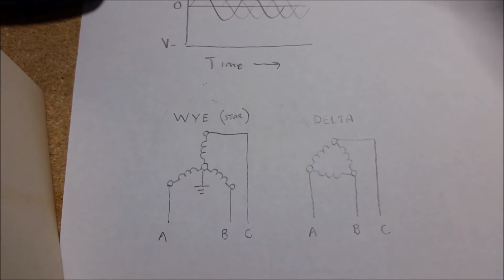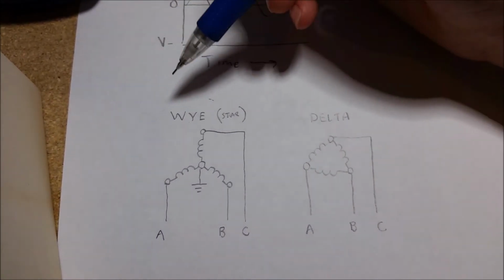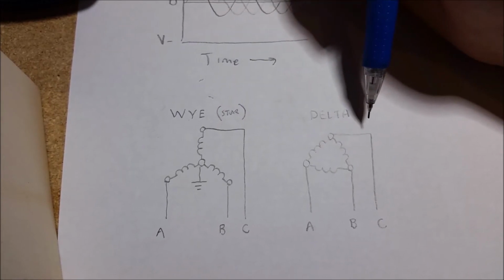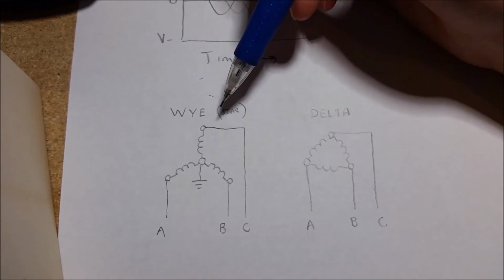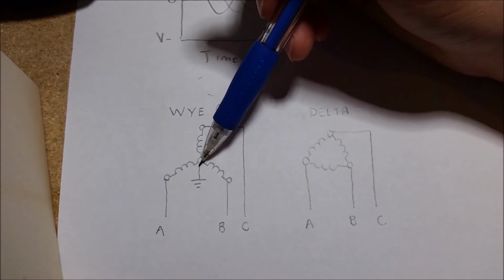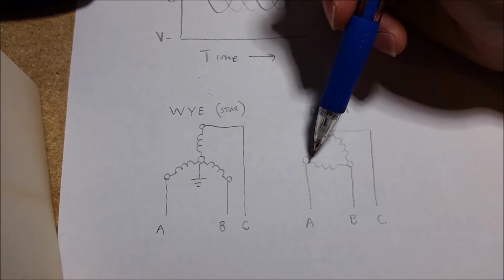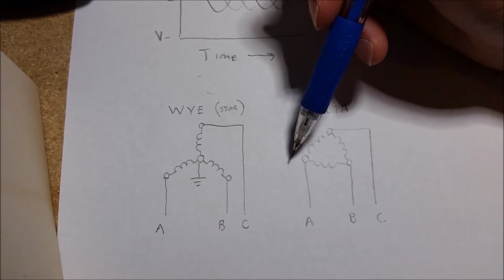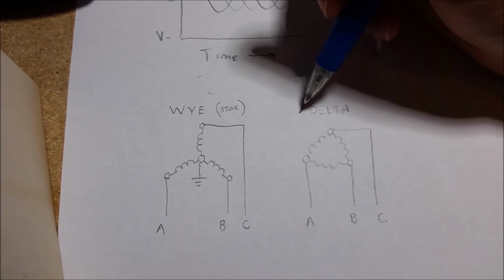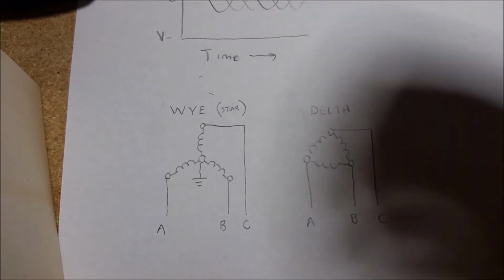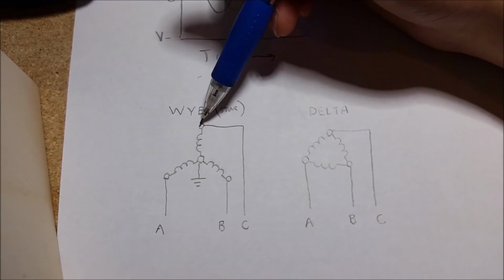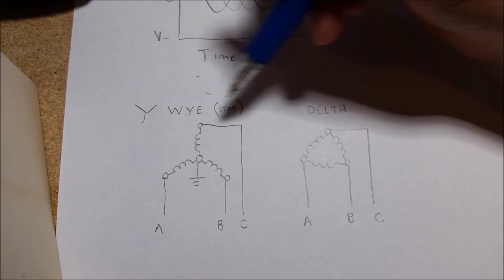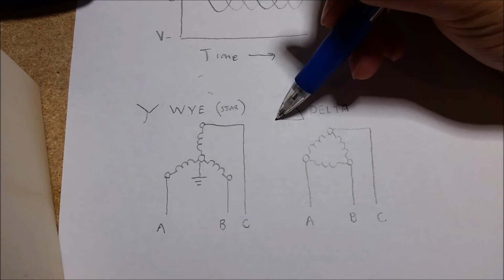Now there are two different ways you can wire the stator in a three-phase generator. You can either use the Y configuration, also called the star configuration, or the delta configuration. The star configuration is the most common because it's easy to ground the system. In delta, of course, all you have are the three phases, and so ground would need to be one of the phase conductors. And for obvious reasons, it's not very practical to ground an actual conductor. And so that's why we use star. And these configurations have these symbols. Y just literally looks like a Y, and the delta configuration looks like a triangle.